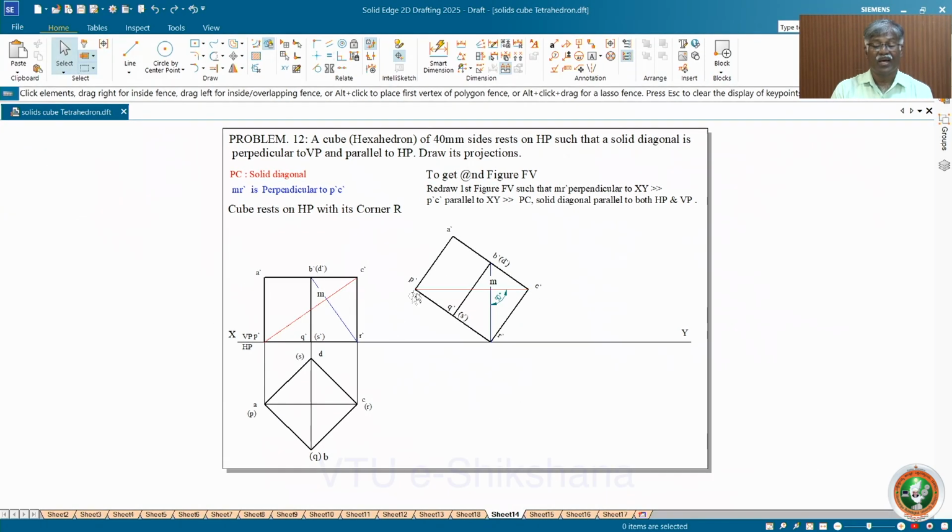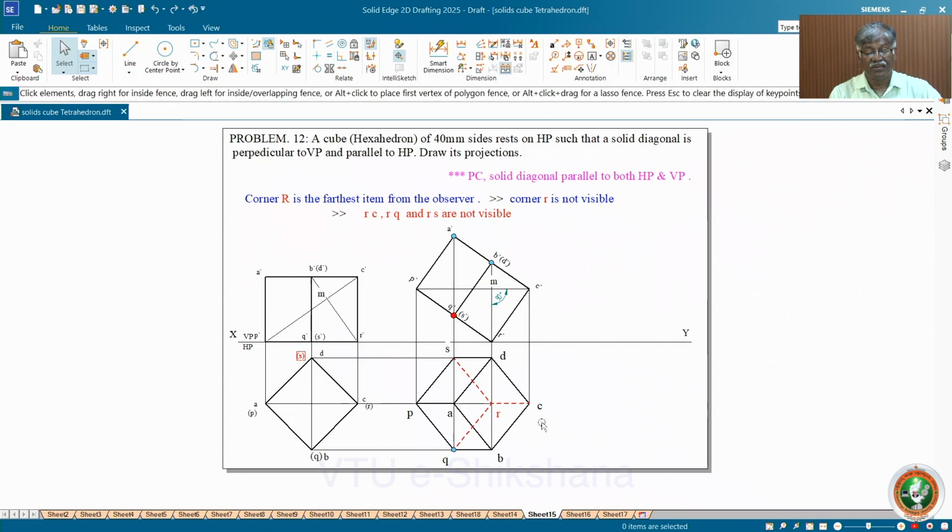Now that's what I have given here. Okay, so you see that this is 90 degree, definitely. Now you project it and get the top view. Okay, so as I told you earlier, you will get 4 lines only. 1, 2. Similar to this, we have A dash coinciding with Q dash, S dash, one more line, and P, one more line. Okay, so then draw the top view with light lines, and then see that the top face is visible. Then the boundary is completely dark, and the invisible lines, surface edges other than boundary lines, are dotted.